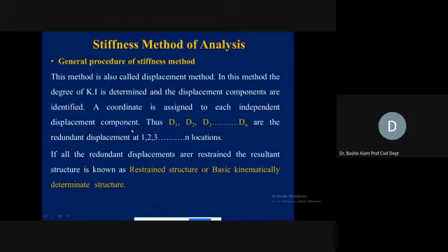And then we come to the kinematically determinate structure, and instead of the hinge support, we put a fixed support now. If you fix something, it means you are stopping both translations and rotation. But by labeling D1, you are showing that originally those two translations were already stopped. But now by providing this fixed support, we are only restraining the rotation. So this will be restrained.